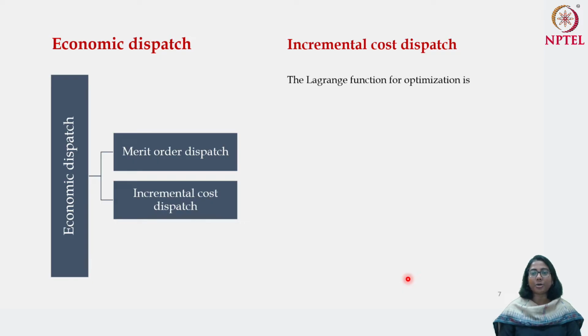For the optimization problem, let us set up the Lagrange function in the following manner. L is the Lagrange under consideration. We need to minimize this total cost. Therefore, the Lagrange is written as summation over i of Ci(Qi) plus lambda multiplied by (D minus summation of Qi). If this D minus summation of Qi is set equal to 0, that implies that the constraint is satisfied. So there will be n plus 1 first order conditions and the second order conditions as well.